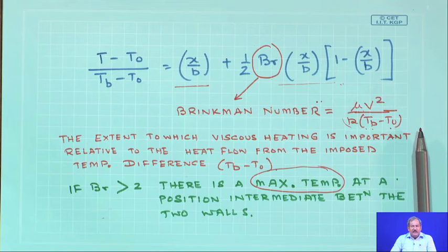So, a simple analysis, a simple problem can give you so many new ideas about how to treat conduction, how to use the equation of energy, how to cancel the terms which are not relevant, and see the importance of conduction when there is flow present, but in a direction perpendicular to the heat flow.